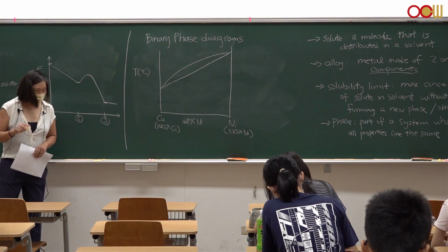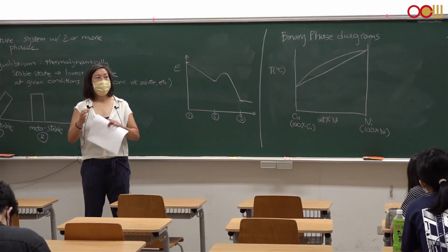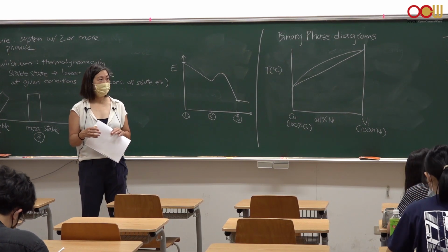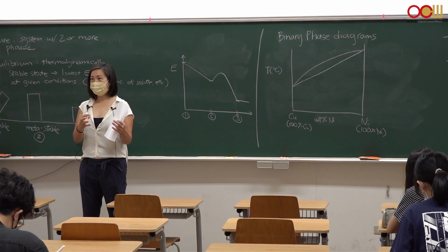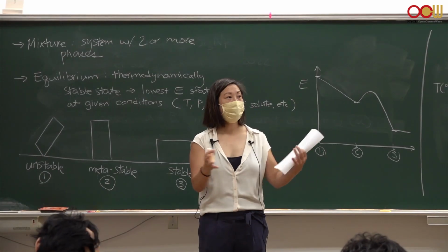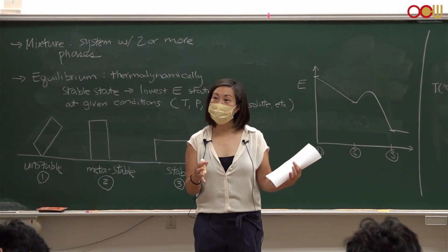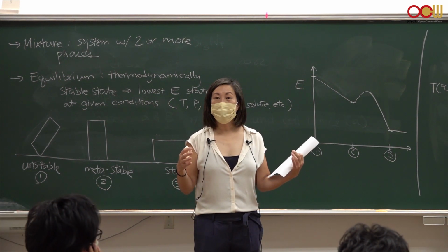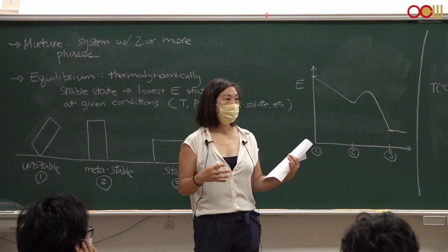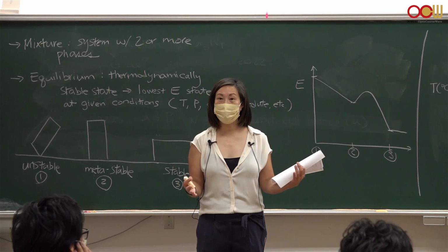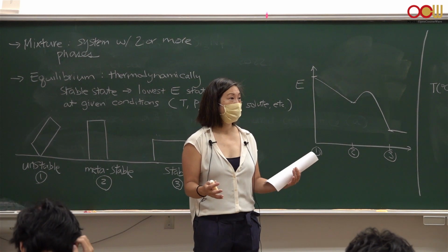Nickel and copper have very, very similar atomic lattices. They have the same crystal structure, and the size of the atoms are very similar, and they have similar electronegativities. Those two elements are very similar to each other, and so they could substitute for one another in the substitutional sites from 0% to 100% without changing the structure of the solution.